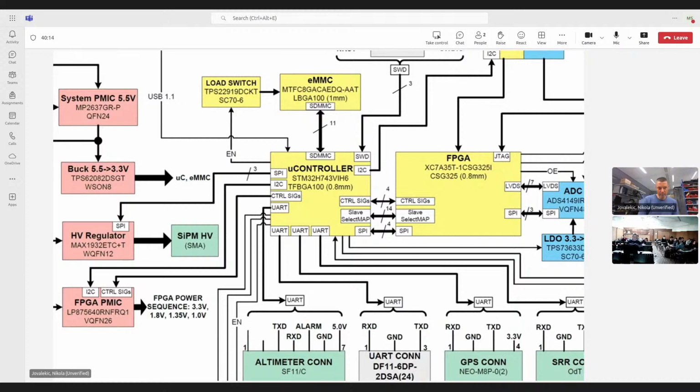Yes, exactly. So what was our approach here is the following. When you apply a battery or you apply a power supply over micro USB, you will just bring power supply to the microcontroller, and that's all. The rest of the board is literally dead. So nothing is powered up. You don't have a power supply. You don't have anything. So in order to power on all other devices on the PCB, you need to write code in the microcontroller which will handle that in a proper manner.